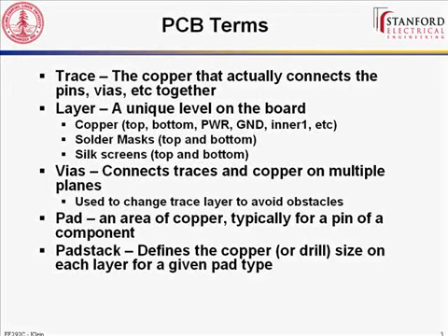If you have surface mount components, like the resistors and capacitors and even ICs that are on your development boards, you'll notice they sit on top of the board, they solder onto a pad, the pad goes off in a trace, and that's it. So the pad stack for that component will have information inside the top layer, which is where the actual pad is that you solder to. It'll have information on the solder mask layer for the top, telling it where not to put solder mask around the pad. And it'll have maybe some silkscreen showing the outline of the component. So if you look, all the components on your board are outlined like the resistors and capacitors. But for example, on the drill layer, or the bottom layer, or the inner layers, there's no information in the pad stack for these surface mount components, because they don't affect those layers.